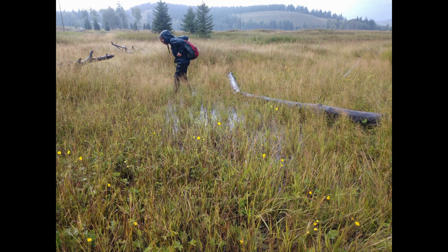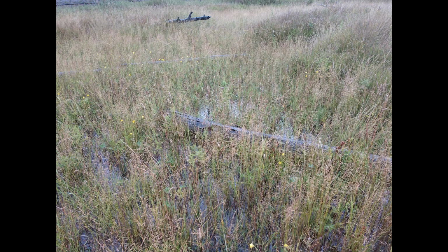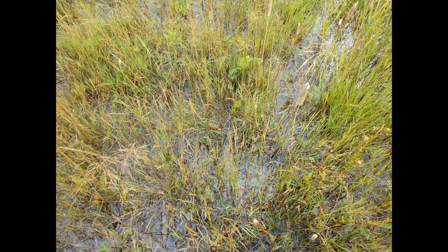The downstream wetland has the shortest hydro period because of a thin layer of silt over gravel. This has become an ephemeral wetland. The ephemeral wetland is a wet meadow wetland during late summer and early fall. People have been telling me that the ephemeral wetland is a failure because it dries in the summer.